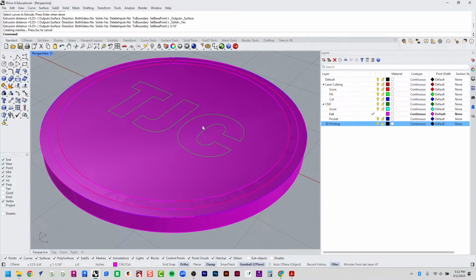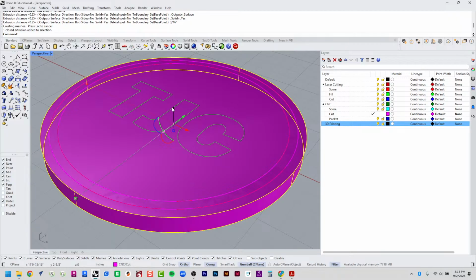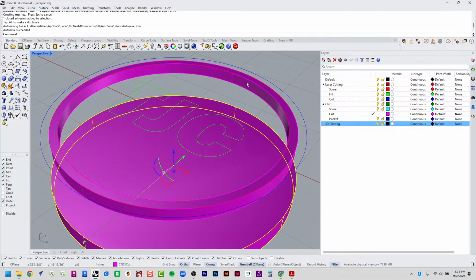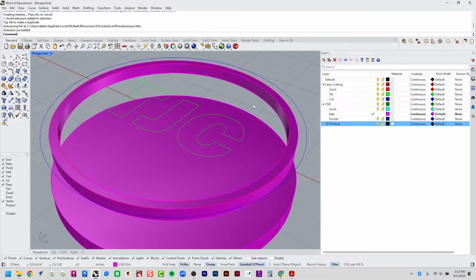The reason why I can't perceive that new piece of geometry is because the face of that new piece of geometry and the face of this 4-inch diameter, quarter-inch thick circle are planar. If I were to select that outer coaster and use the gumball to move it down, voila, there is that ring. The top of each one coincides, right? They're both planar. I'm going to hit undo.